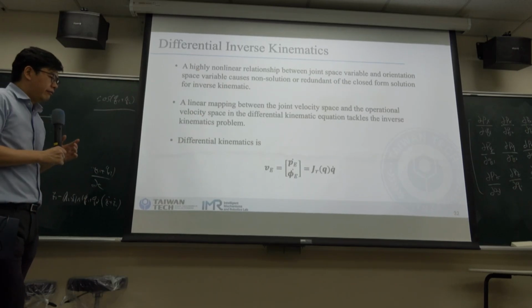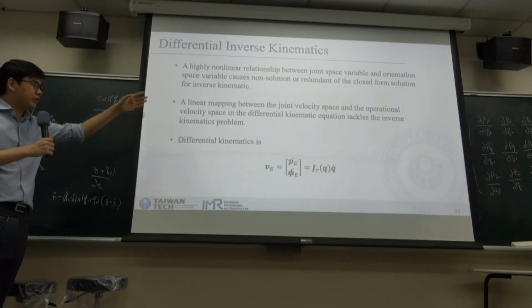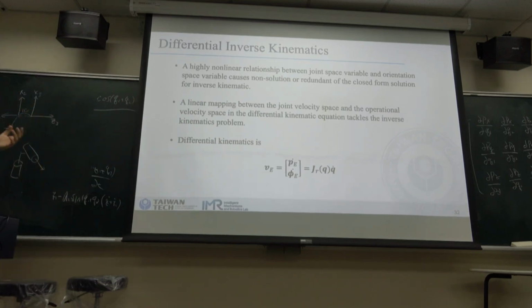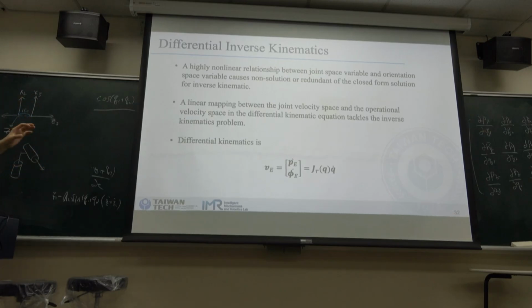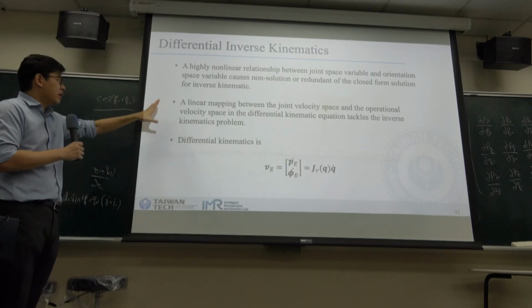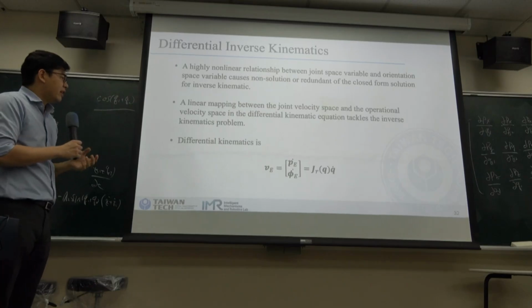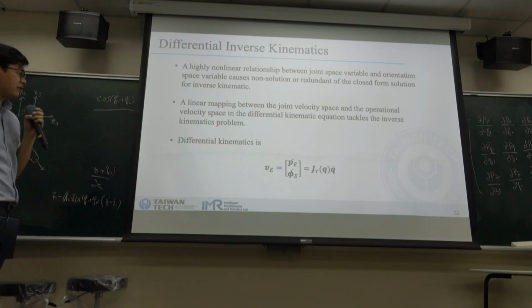And I think we introduced the inverse kinematics last week. Last week, we introduced the analytical inverse kinematics. Here we will introduce another, the numerical inverse kinematics. Normally, if you go into industry, all the industrial robots use the numerical method. So this is the basic, the fundamental formulation for the differential inverse kinematics.